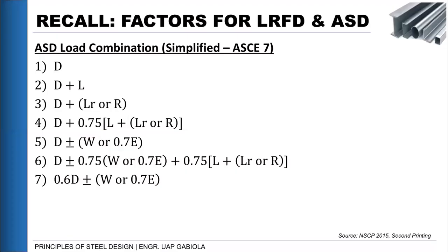It means that maybe this load combo will not happen all the time on the structure. That is why it considers only 0.75 of its capacity. And then as you can see here for the earthquake, the factor became 0.7, because using the earthquake equations to calculate the seismic forces or base shears on our structure is based on the LRFD approach.